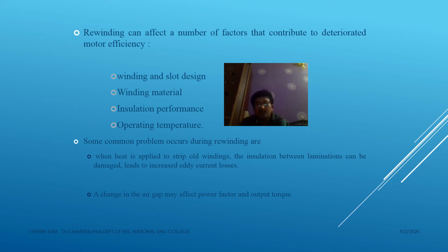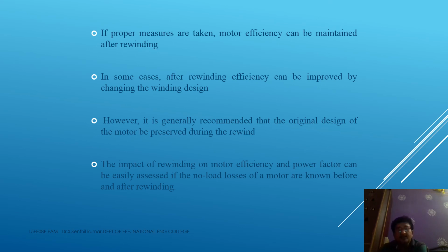While rewinding the motor, care should be taken, and proper measurements should be taken so that the motor efficiency can be maintained after rewinding. The previous level of motor efficiency before rewinding and the efficiency after rewinding should be recorded, so this data can be compared and the motor efficiency before and after rewinding can be confirmed.